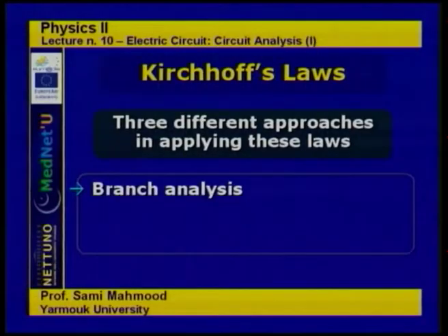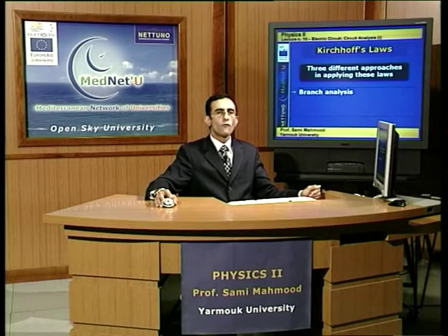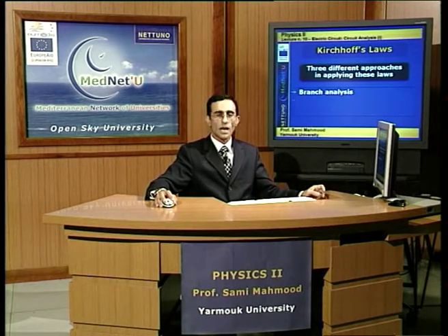We have the so-called branch analysis, where we set up a number of simultaneous equations that is equal to the number of branches. So we have a number of equations that is equal to the number of unknown currents, each one flowing in a branch of the circuit. And the solution of these equations would give us the full solution for all the currents flowing in the branches. This approach is called the branch analysis.